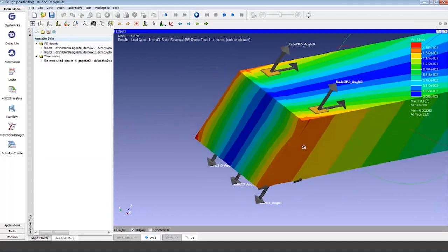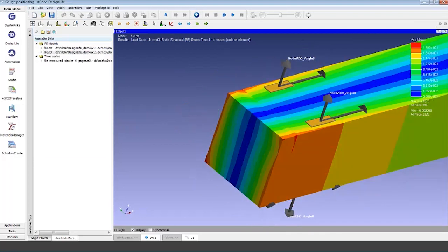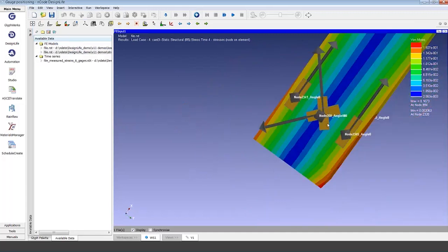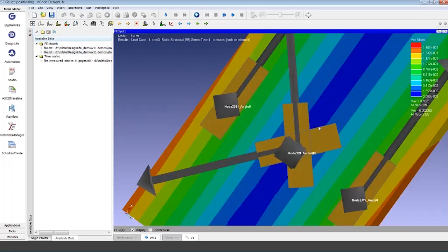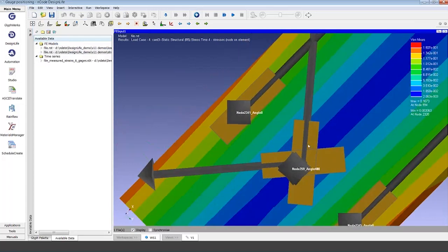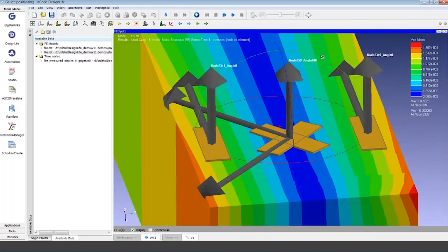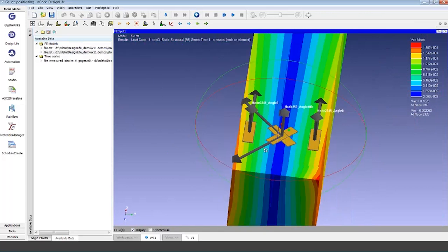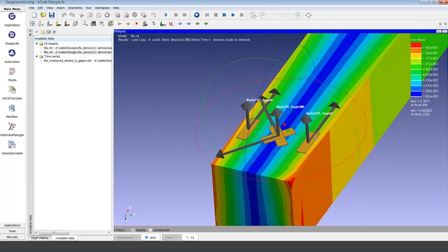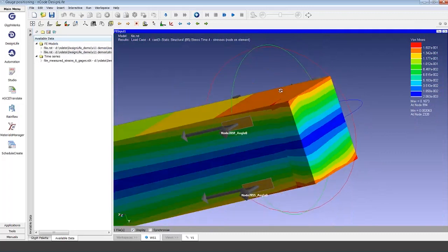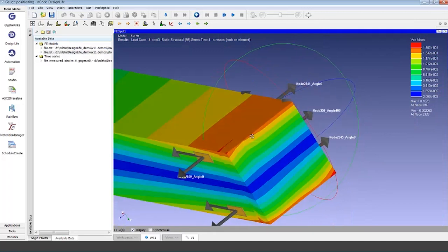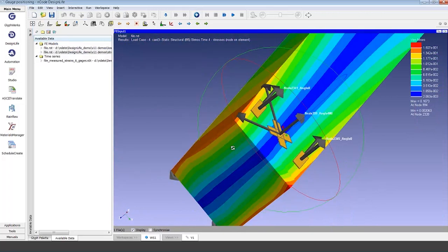We can see what's going on, and we have a series of strain gauges. So 1, 2, 3, 4, 5, 6. Those are 6 gauges right here. Let's take a little bit closer look. Right, so we have six strain gauges, and you can see the location of them has been chosen to be sensitive to those 4 different degrees of freedom of loading. You can imagine we have gauges at the top and bottom surfaces to look at bending. Their differences will help us understand bending on different axes. Their averages will help us understand axial loading. So not too hard to figure out why gauges are in certain spots.